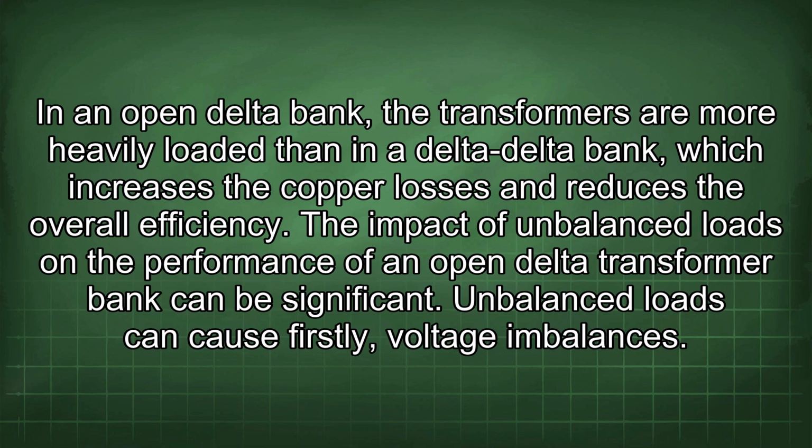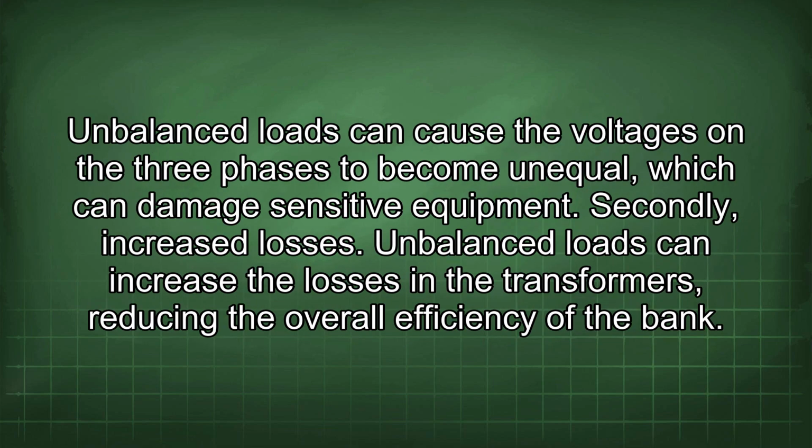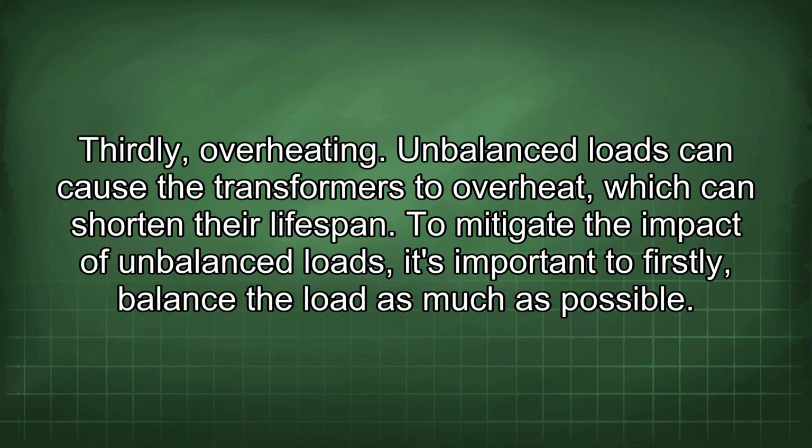The impact of unbalanced loads on the performance of an open delta transformer bank can be significant. Unbalanced loads can cause, firstly, voltage imbalances. Unbalanced loads can cause the voltages on the three phases to become unequal, which can damage sensitive equipment. Secondly, increased losses. Unbalanced loads can increase the losses in the transformers, reducing the overall efficiency of the bank. Thirdly, overheating. Unbalanced loads can cause the transformers to overheat, which can shorten their lifespan.